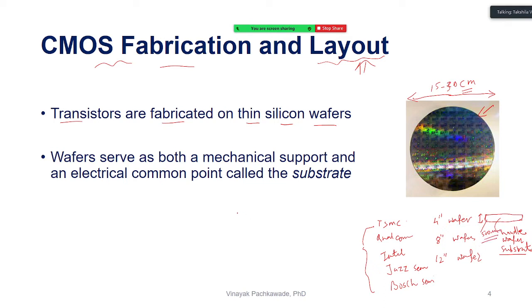If I have to draw this silicon wafer, and if you remember from the previous slide, somewhere here we are going to fabricate our transistors. This is NMOS and PMOS. This is called a substrate. It is basically 500 micrometer thick, so small. And you can imagine the thickness of these regions, how deep they can go. They are usually about 10 to 20 micrometers based on the technology.